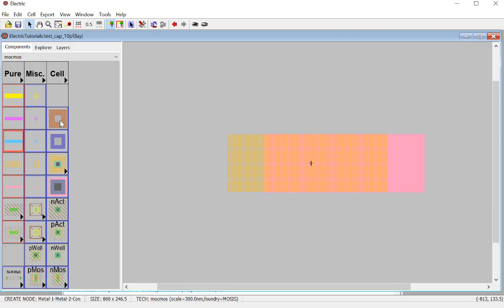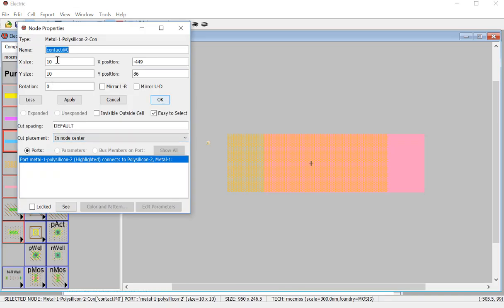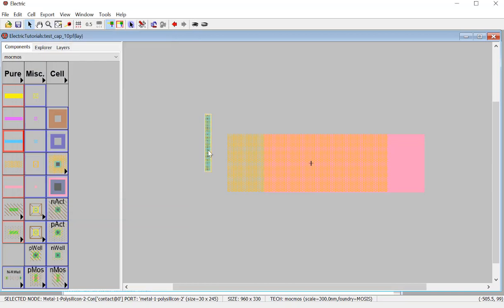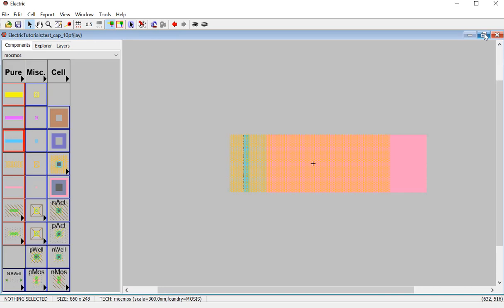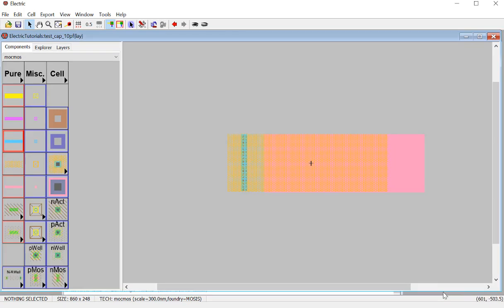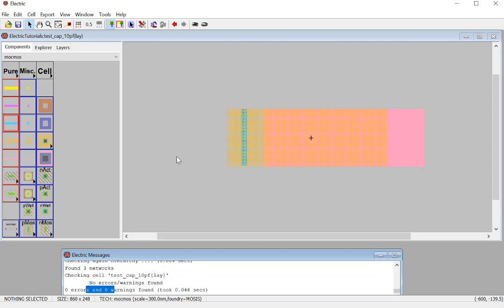And so this is all right, and we need a connector, metal one connector, and this one should be the same width, which is the y-axis. It should be 245, but we want to make this one a little bit larger than that. So let's make 30. Okay, and I will place it here and right-click this poly tool to make a connection and press F5. No errors. So it's not reporting any errors here. All right, so no errors.